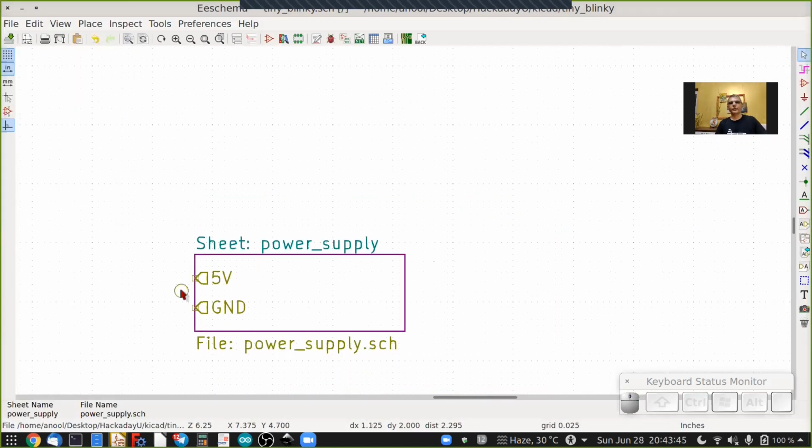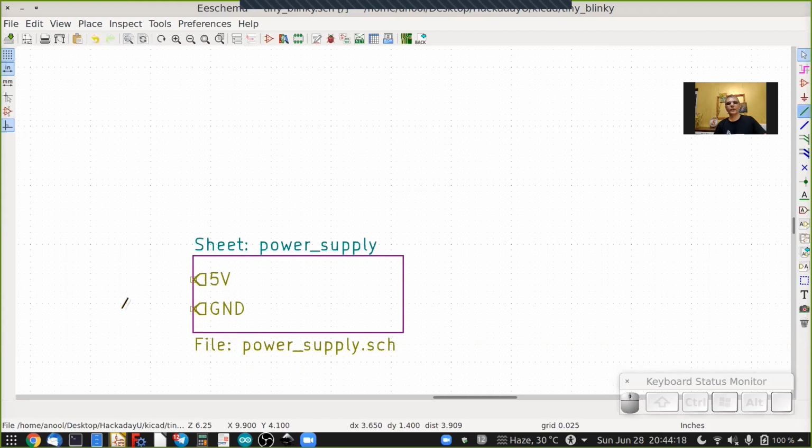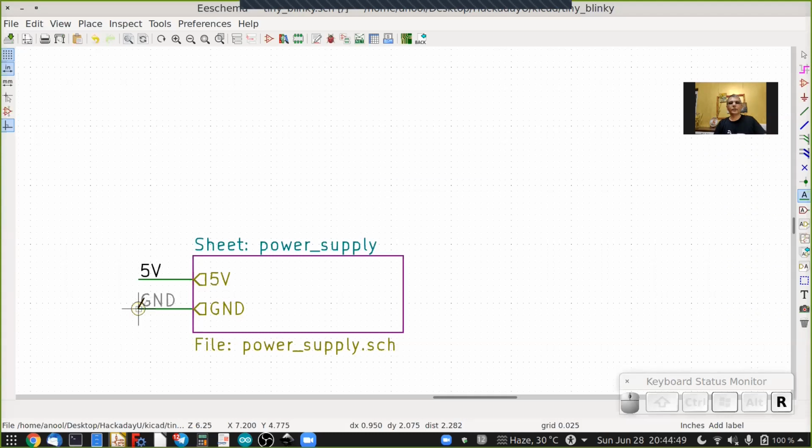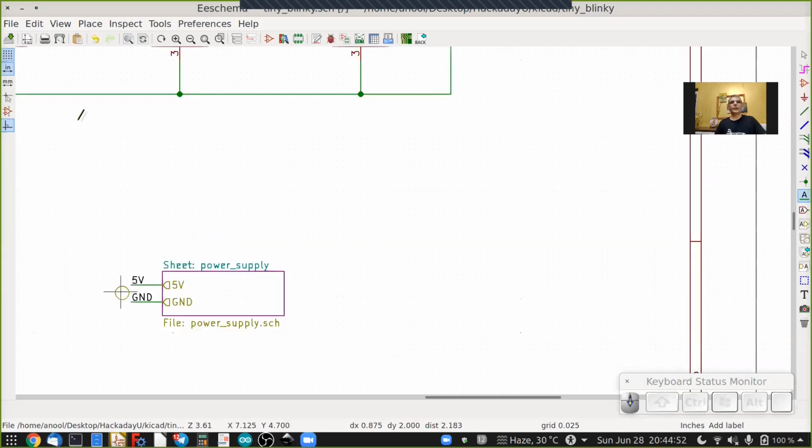At this point, what's left is, let me click on the place wire icon, draw a short stub like so, draw a second stub like so, then go to place net label, click here once, click 5 volts, rotate it so it lines up like so, place it there. The other one, click once, type GND, enter, rotate twice, click and place. So that places the net labels on these corresponding hierarchical labels. That finishes the whole process of drawing a hierarchical sheet.